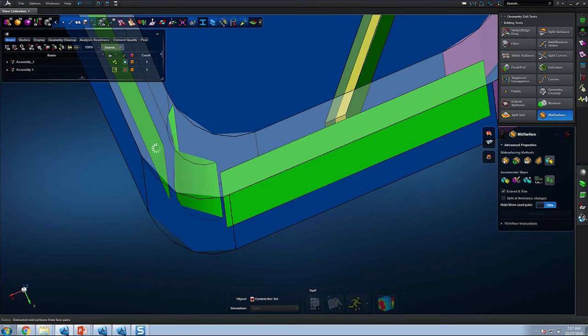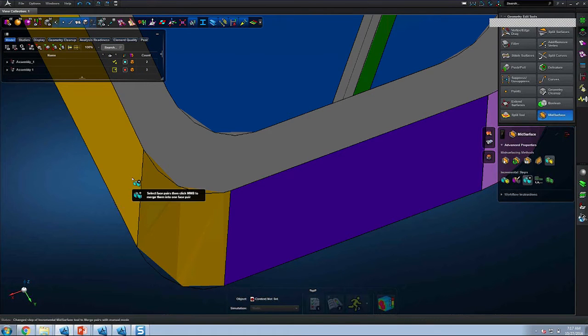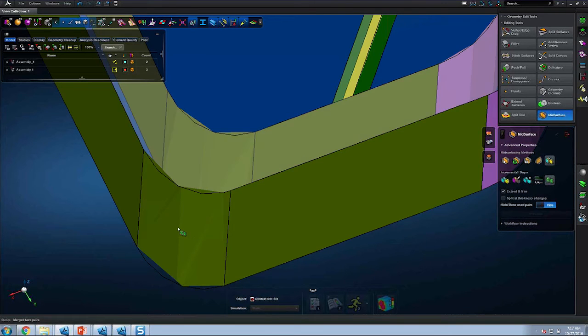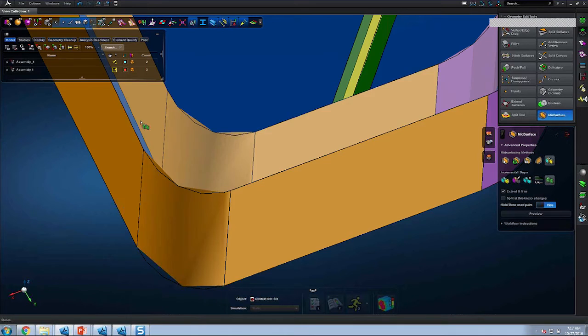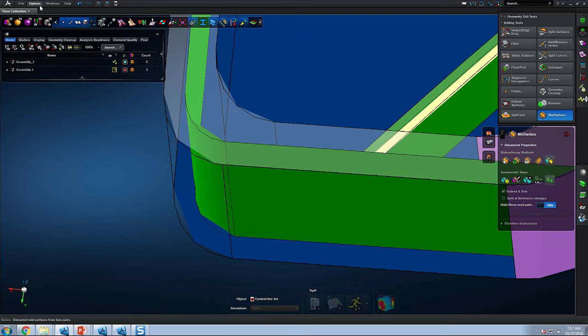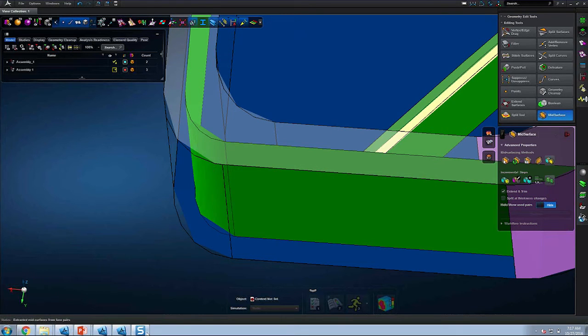And right now what I'll go ahead and do is undo the step I just made, and then I'll combine the pairs on the outer portion of the screen. So let's go ahead and undo this. And let's go ahead and merge these pairs. So 1, 2, and 3. And then we'll go ahead and extract this midsurface, and you'll find that now we have a nice running continuous midsurface here around this corner. So again, this is the incremental approach, or the so-called semi-automatic approach.